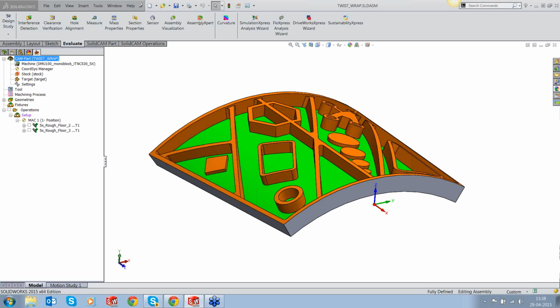We have some nice new strategies in 5-axis for roughing, and that's called multi-axis roughing. And there are some enhancements to the existing strategies and some very nice functions for converting 3-axis toolpath to 5-axis toolpath automatically. And we'll also see some nice things that have come up in swarfing, like rotating the swarf toolpath, providing a new kind of Gouge check for the swarf toolpaths. So there are a lot of things that we are going to see in this webinar.